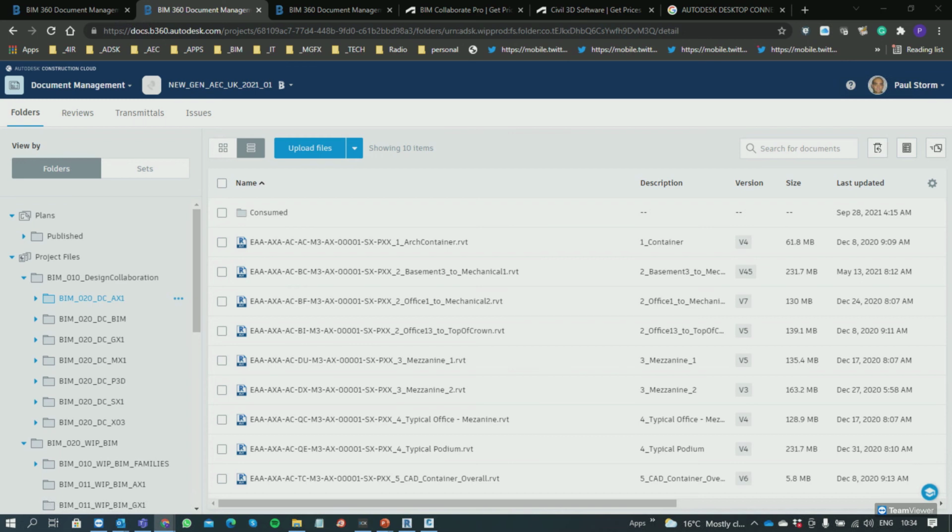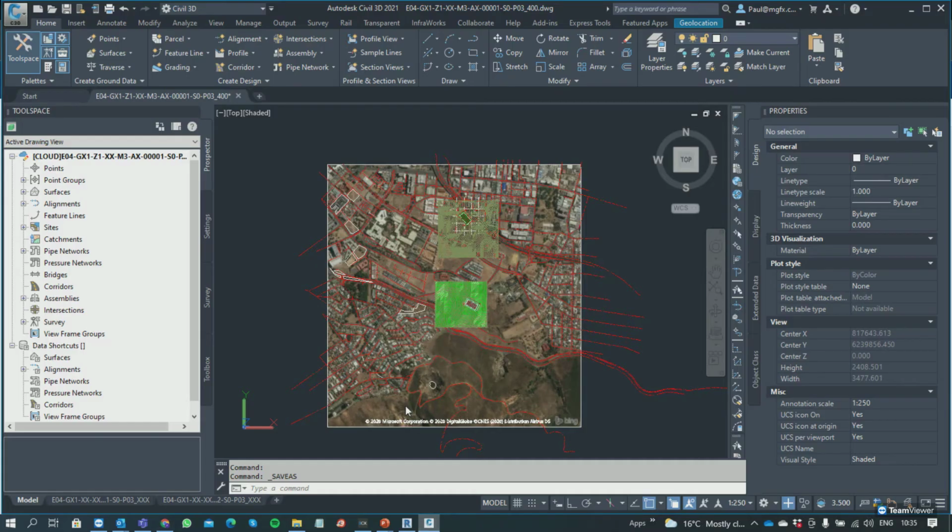And I downloaded a file where somebody's gone to some trouble to set that coordinate system up. It's got an offset from the origin and it's very specific. And while one can open a Civil 3D file to see those coordinate systems, they are not readily available. The interoperability between Civil 3D and InfraWorks, for instance, does not work.